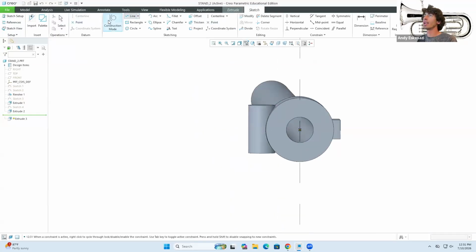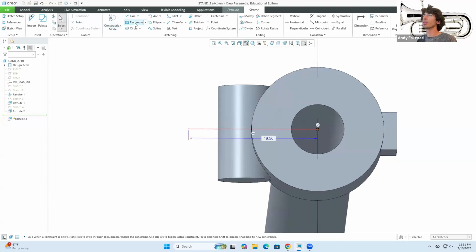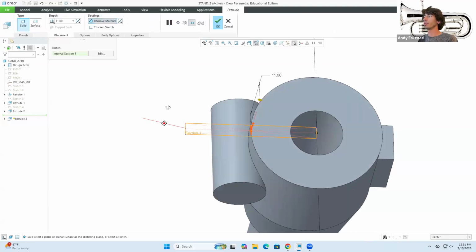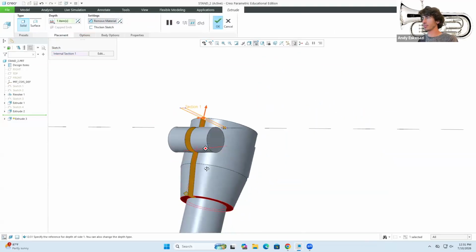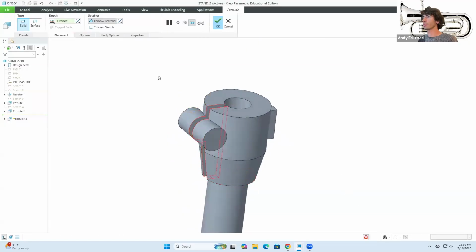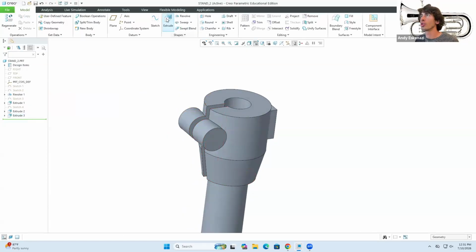and we'll draw the last line, which is gonna represent the cut. So then rectangle, roughly here. That was like 20. This was 2. And we are going to remove material with reference to that face. Perfect. So now the same procedure, actually we're not done.